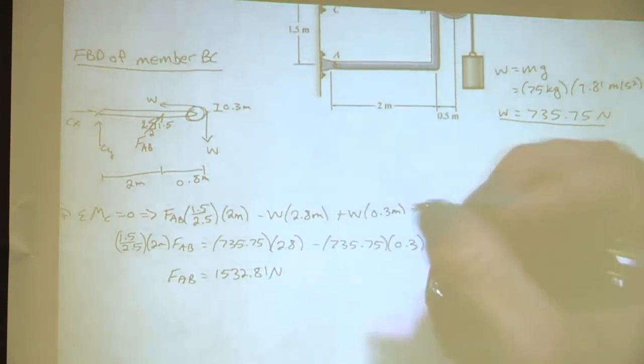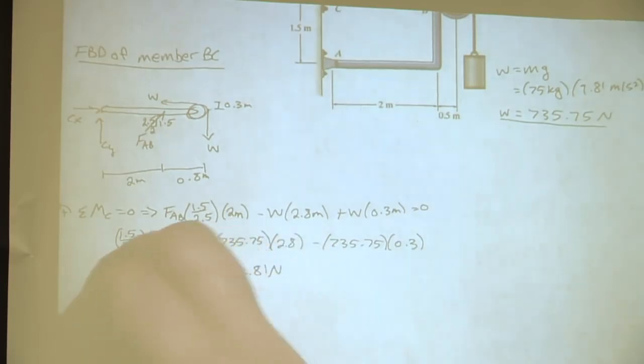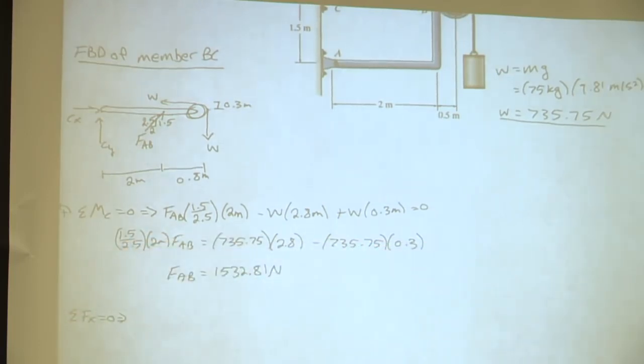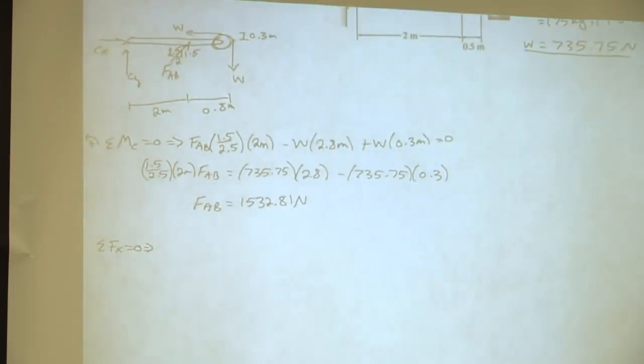Awesome, newtons. Okay, so now we solve for FAB. Is there anything else we need to solve for now? Okay, awesome, so support reactions. So how can we solve for them? We can do moments about B. Okay, awesome, we could do moments about B. Is there anything else that might be simpler? Okay, awesome, so sum of moments with the X and the Y, we don't have to worry about those perpendicular distances. So let's start with, so how many terms should we have in this equation? For X, only 2. So I heard 2 and I heard 3. 3. So which ones?